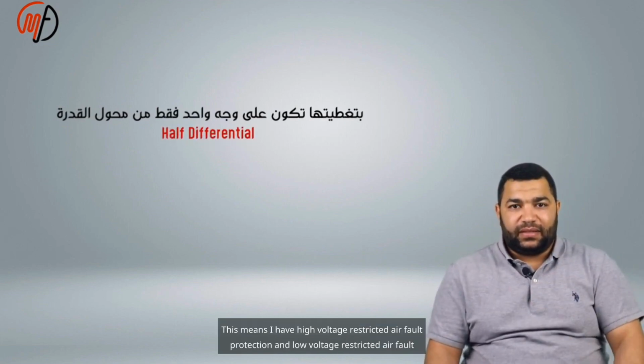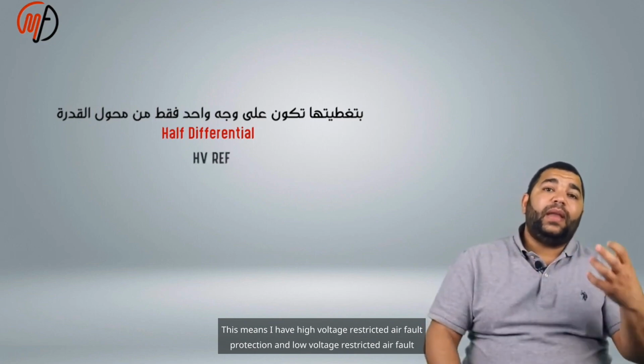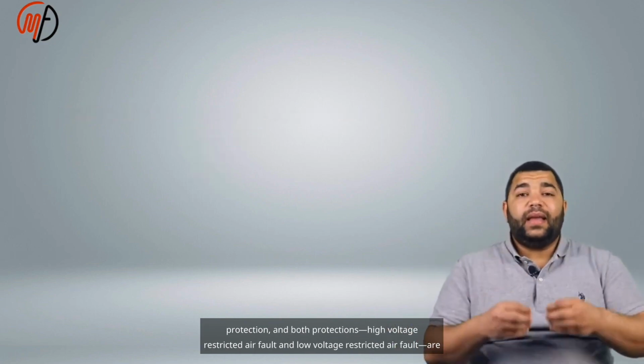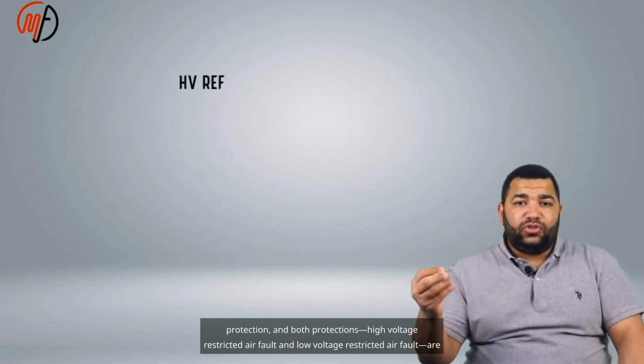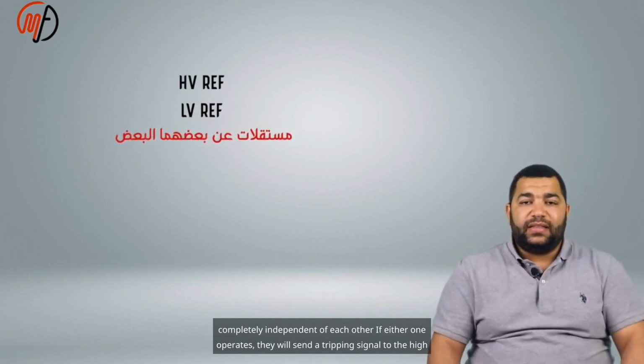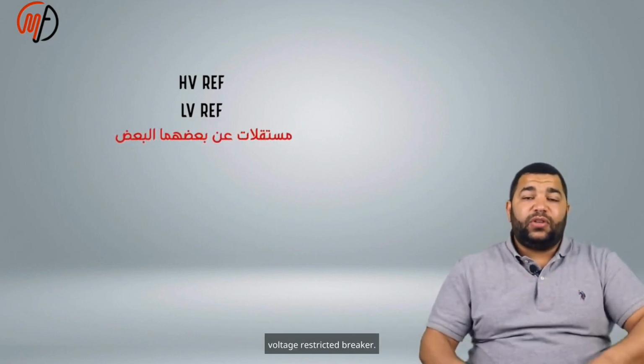This means I have high voltage restricted earth fault protection and low voltage restricted earth fault protection, and both protections are completely independent of each other. If either one operates, it will send a tripping signal to the high voltage breaker.